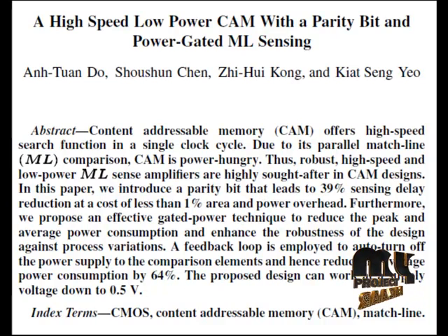Next, the search line drivers broadcast the search word onto the differential search lines, and each CAM core cell compares its stored bit against the bit on its corresponding search lines. Match lines on which all bits match remain in the pre-charged high state. Match lines that have at least one bit that misses discharge to ground. The match line sense amplifier then detects whether its match line has a match or miss condition. Finally, the encoder maps the match line of the matching location to its encoded address.